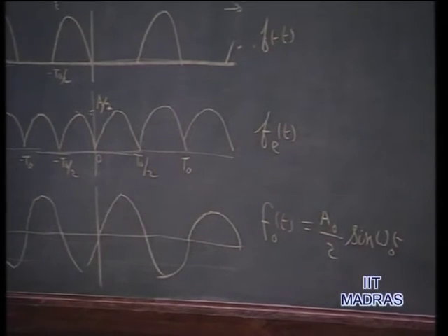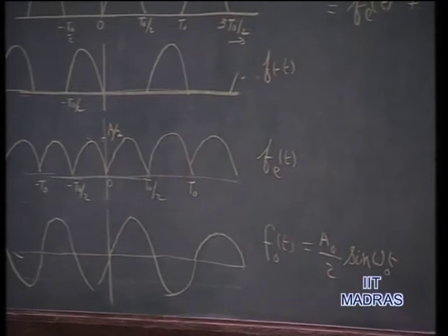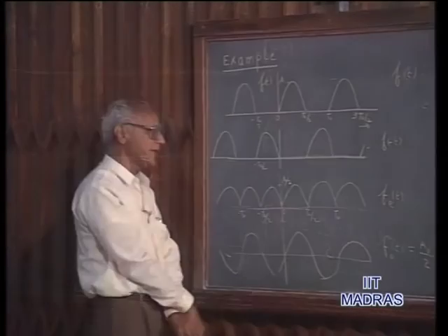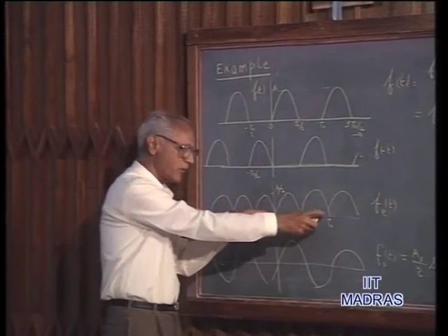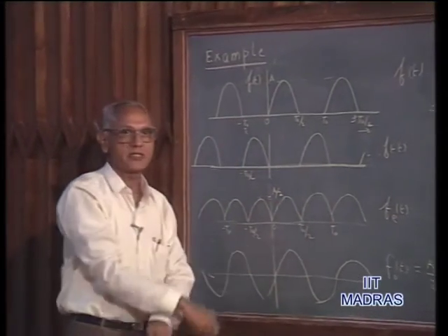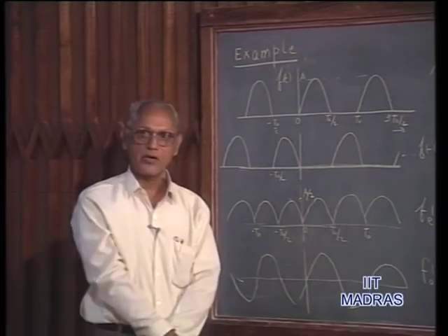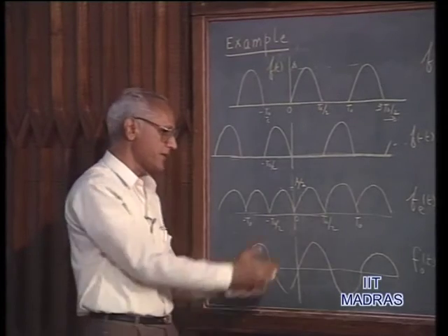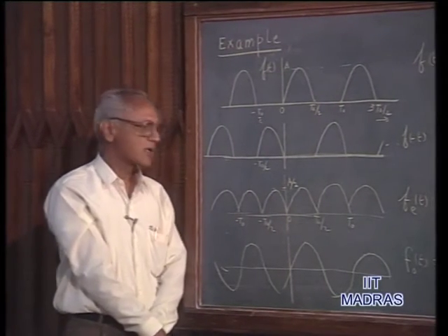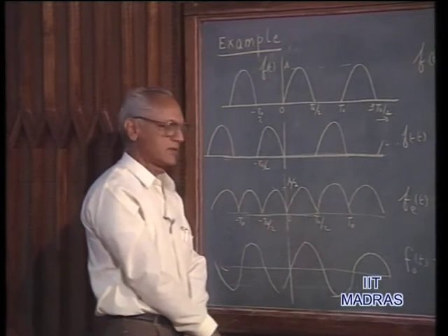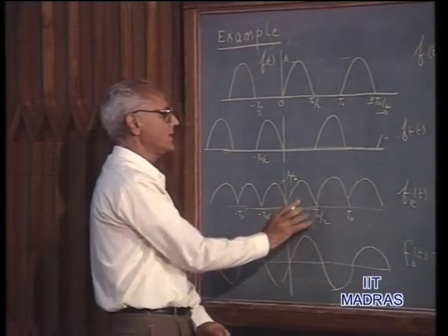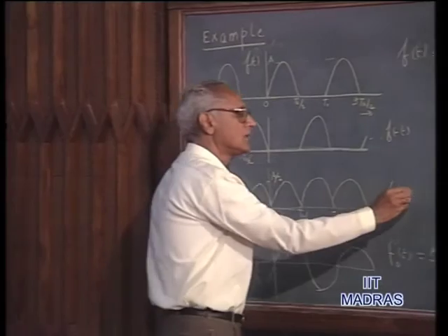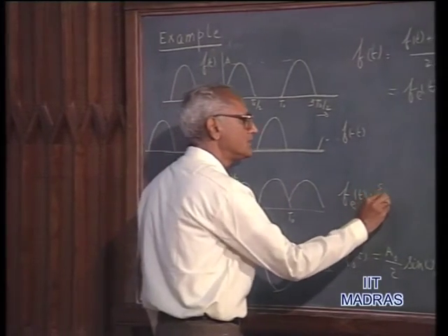And you also recall that we mentioned in the last lecture that whenever you are having a waveform like this, we would like to still continue this as the basic period, not as this, because we are going to relate this basic period to the parent waveform from which it is generated. After all, we want to talk about fundamental frequency in relation to this. Therefore, we will continue to have the same fundamental frequency when describing this waveform as well. Consequently, we regard this as the basic period, in which case the function f of t happens to be f of t plus T naught upon 2. Therefore, this will have only even harmonics present.